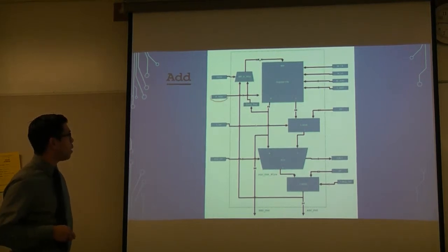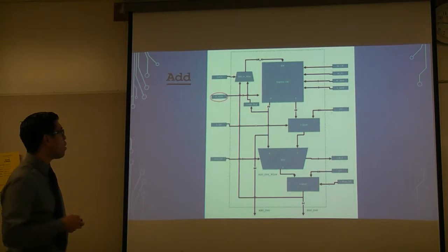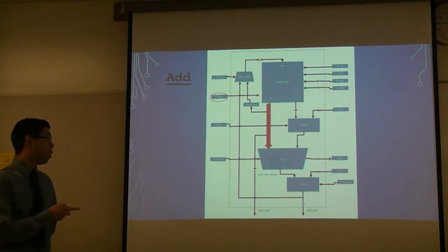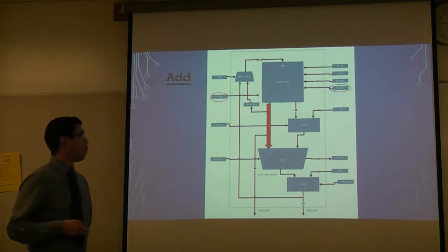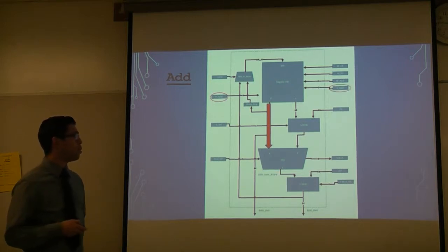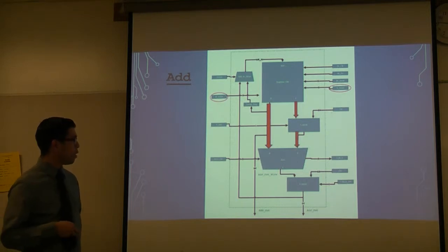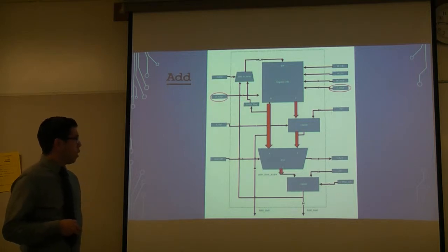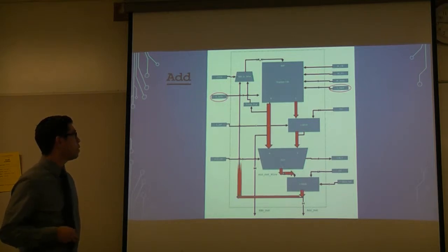So one of the things, first off, wherever the R address is pointing to, that data goes into the R side of the ALU. Wherever the S address is pointing to, the source 2 register, that goes into the S MUX, and then that goes into the ALU on the S side. Comes out of there, whatever, the operation here would be R plus S.